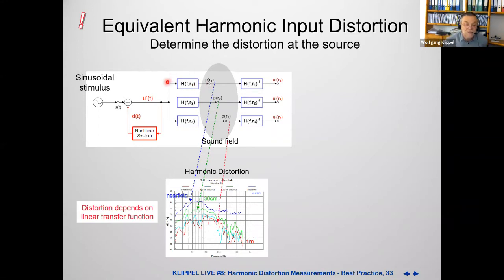But now we are taking the complete linear response, including the Thiele-Small parameters and normal behavior of the loudspeaker. So effectively here you see the -1 in the exponent. This is canceling out. We are effectively at this point as close to the input, after the distortion is added. And now the interesting point: those signals should be identical if this is true.